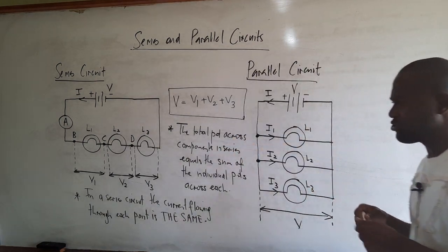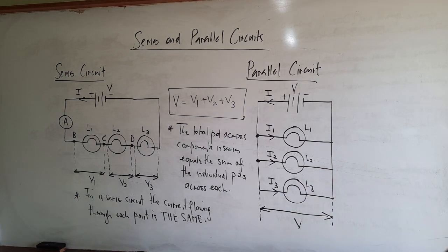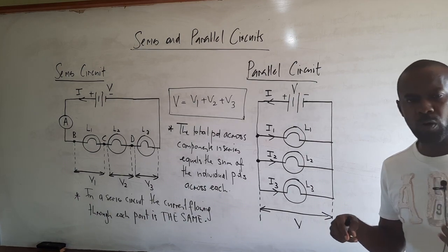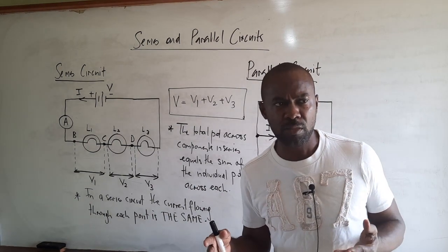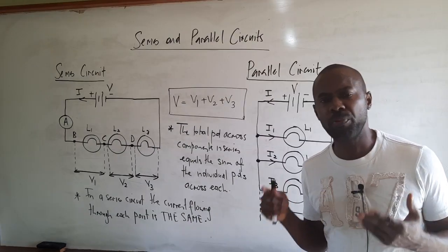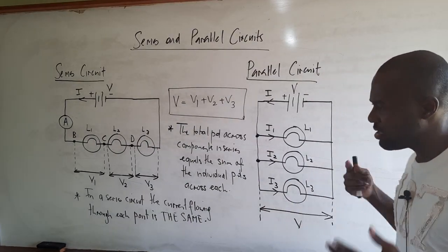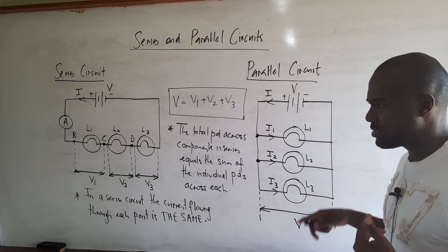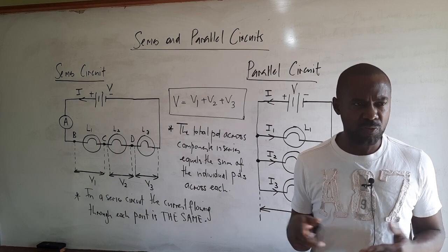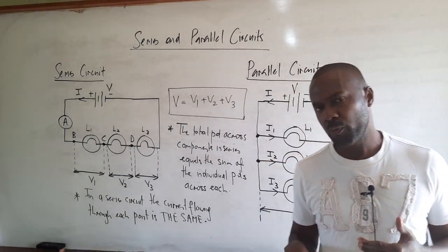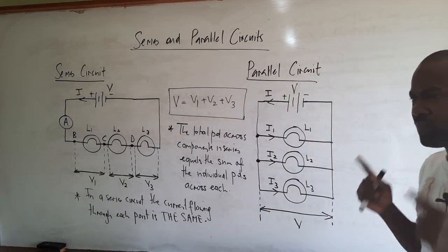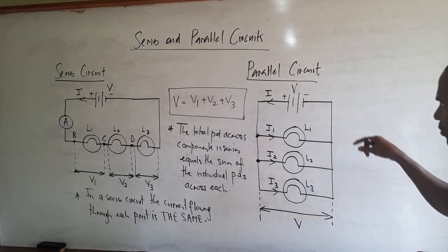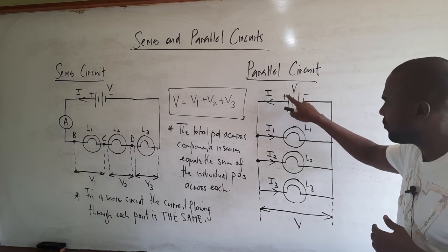Now, once again, the battery is driving a current. And of course, remember that when looking at circuit diagrams, what we indicate as our direction of the current is what we consider to be conventional current, which of course is the direction that positive charge would flow, right? So despite us knowing that electrons are really the mobile charge carriers, we do not indicate the direction of electron flow in a circuit unless we're required to do so. We typically indicate the direction of conventional current, which would basically be the direction that positive charge would move, right? So we have the conventional current I flowing around the circuit.